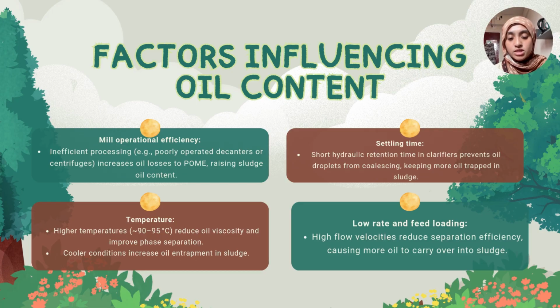And the third one is temperature. High temperature reduces oil viscosity and improves phase separation. Cooler conditions increase oil entrapment in sludge. And the last one is flow rate and feed loading. High flow velocities reduce separation efficiency, causing more oil to carry over into sludge.